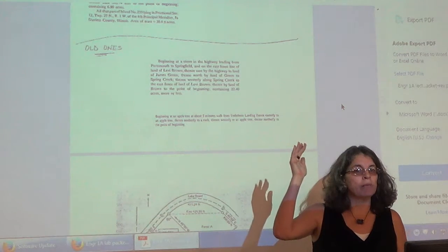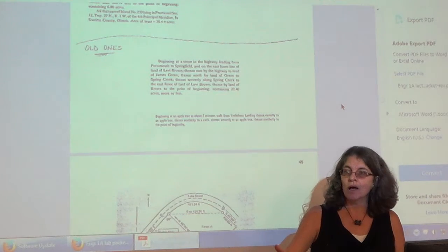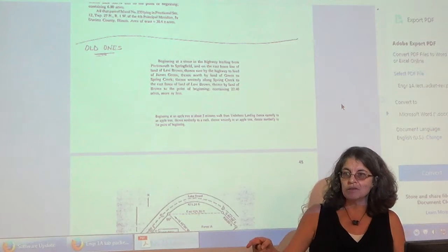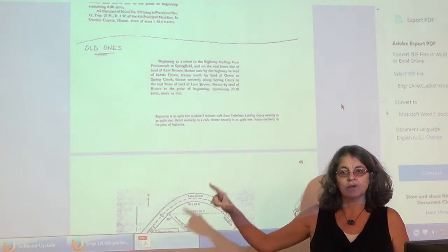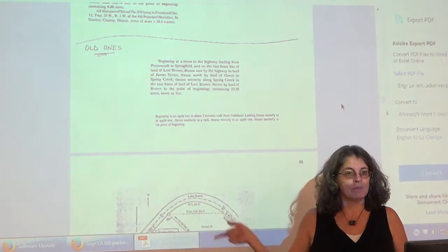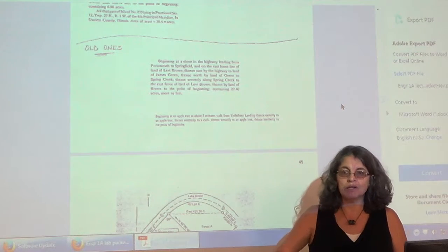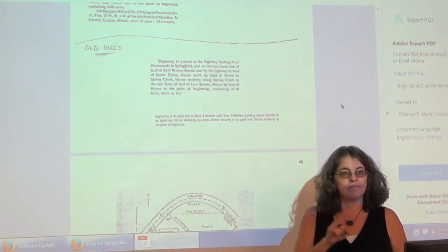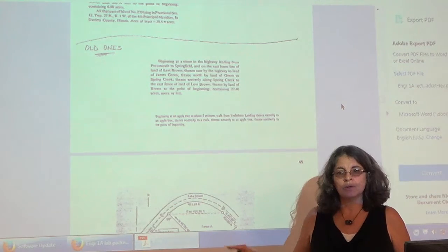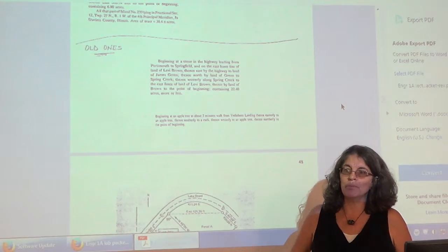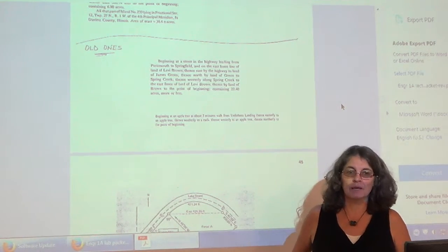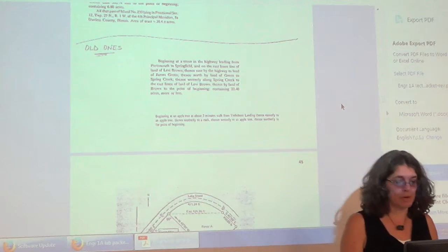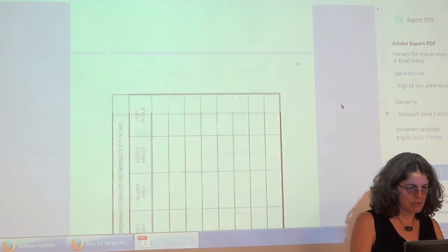Beginning at a point marked by an iron pin, crossing the pavement. Thence, bearing distance to an iron pin; thence, bearing distance to an iron pin; thence, bearing distance to an iron pin; thence, blank, blank, to point of beginning. Okay, so if I give you a little sketch, you can write the metes and bounds description.